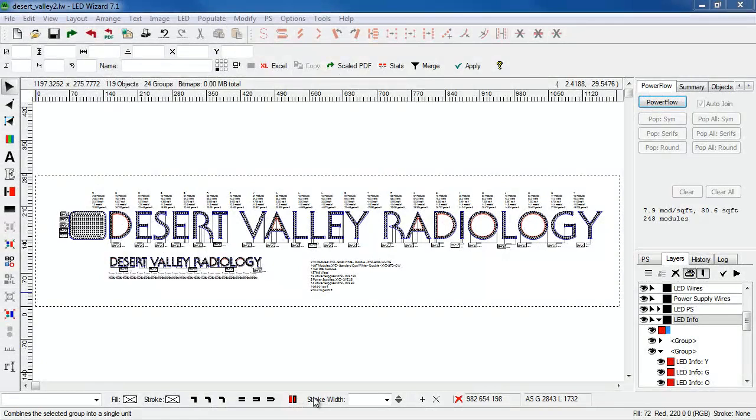The next step in the workflow is to merge our design with our title block template. So I went in here and made a few spacing adjustments, just moved this down, moved the summary stats over, scaled them up. So we can now take our custom title block template and merge it into this layout. The title block template can have bitmaps in it, it can have vector graphics, it can have your logo, pretty much anything you want to have in the template.